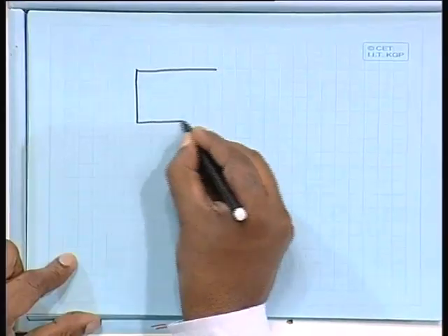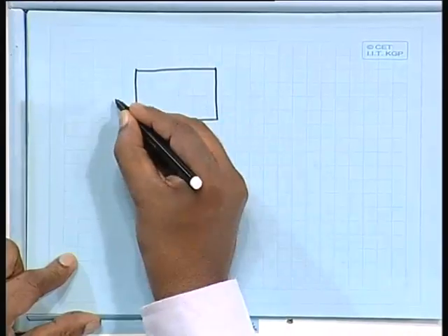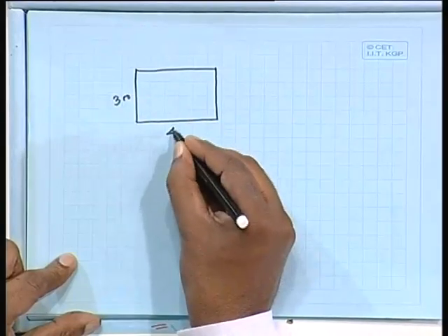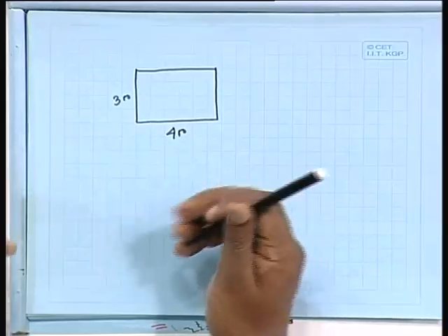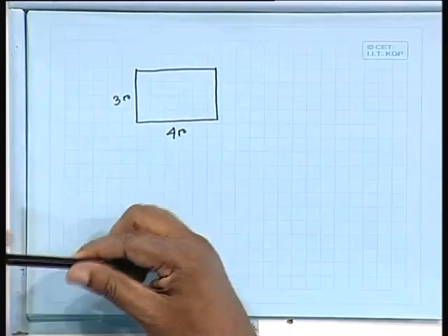Now here, what we do with the interaction curve particularly, I do not go by this curve. What I do actually, I do it directly. This is the section, let us say 300 by 400. I do not go by the percentage of steel. Why shall I use the percentage of steel?